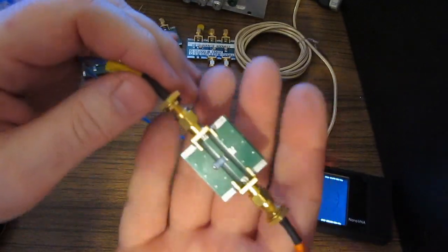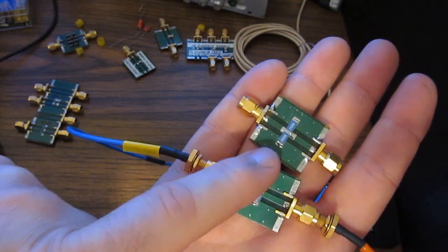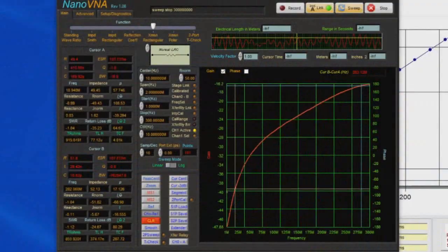This is a 100 milliohm resistor. It's just a single 100 instead of the 250s in parallel. And you can see we're reading, again, a little high. It's reading about 107 or so milliohms, 108. Fairly close, I'd say. Again, we're in the ballpark. So hopefully it gives you some confidence in the measurement.